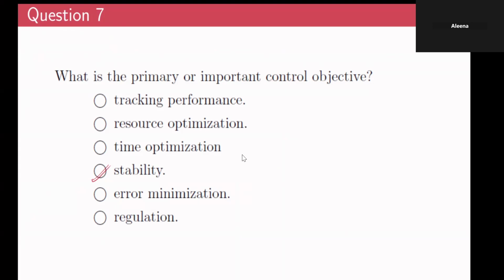A huge spike in control input would force the system to be unstable, and it cannot be recovered. So the most important thing to be ensured for the control objective is stability. And in all the closed loop control schemes that we have discussed earlier, it ensures asymptotic stability, asymptotic stability in position as well as velocity, which they are inherently stable.